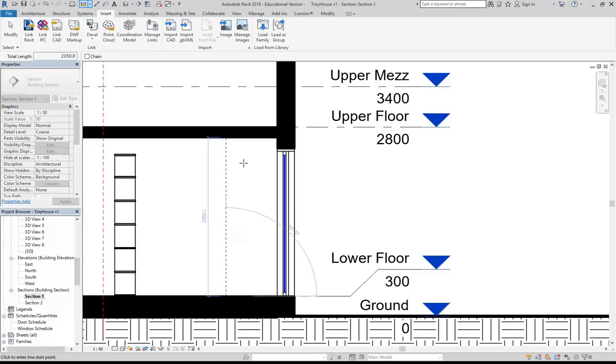Okay, so again, the difference between the levels is 2500, but from floor to, we'll say floor to ceiling at the moment, it's 2350. But we still need to put a ceiling underneath that. That's a floor. And so technically, even though you can build ceilings to the underside of a floor just by lining the floor joists, in Revit, you need to make a separate ceiling object. And we need to know the height that ceiling's going to be and also its thickness.